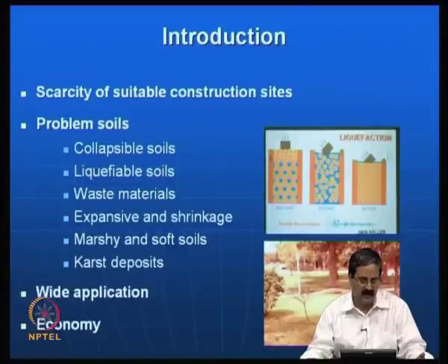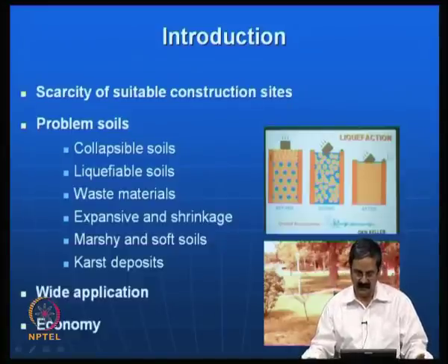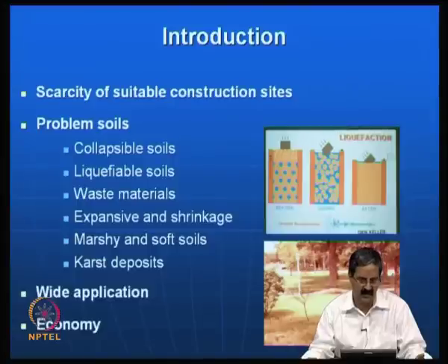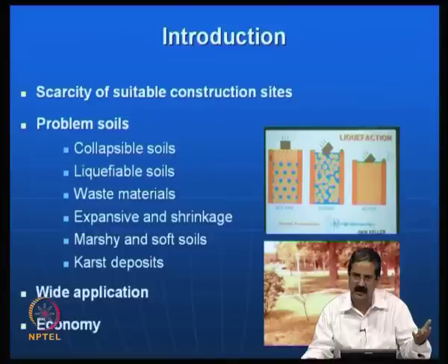You have another type, what is called expansive soils, which I can show you in the figure here. These expansive soils are quite common in many areas, particularly in the Deccan Plateau and in some parts of Andhra Pradesh, where the soils have a tendency to swell, meaning they take a lot of water, and then when you remove all the water, they go to a minimum volume. Liquid limit is the highest water content, in the range of about 100%, and the shrinkage limit could be as low as 10%.